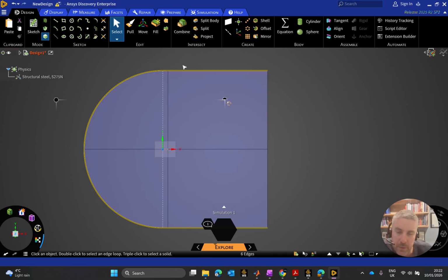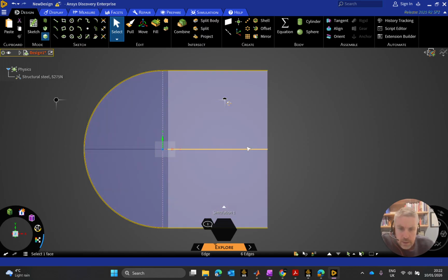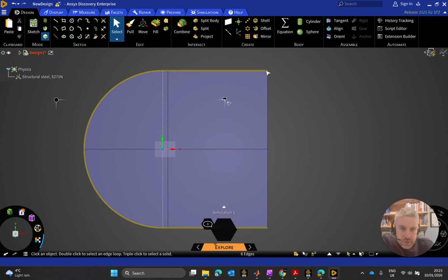Right, that's my inlet. So inlet is kind of a deceptive description of that. Inlet, automatically you think normal to the surface, that air is going to be coming in straight arrows all the way around that. Yeah, that's the way Fluent sets it up as default, but we can change the components. We can change the velocity in a 2D analysis into its X and Y components, and we could say there is no Y component. It's going all parallel here with the x-axis. So up here, all we're saying is that air along this streamline is just scooting the whole way through there. Okay, it's just coming in on straight lines as opposed to coming in. So yeah, absolutely, that can be an inlet.